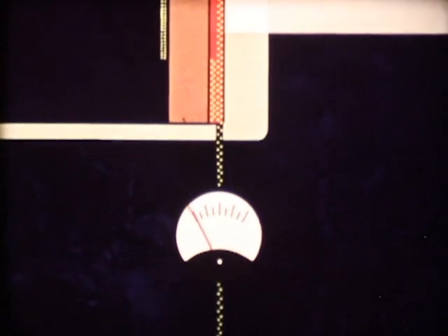When the tube is switched on, the signal plate becomes charged. The light of the scene sets off the photoconduction process and discharge occurs. Where strong light is present, a large discharge takes place. But wherever the light intensity is less, a correspondingly lower discharge occurs. In this way, all the light impressions are stored and then transformed by the electron beam into charge impulses.